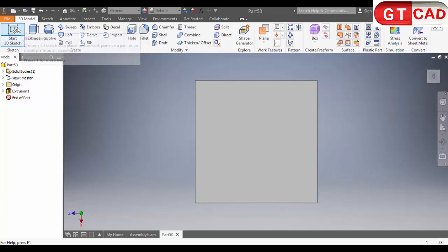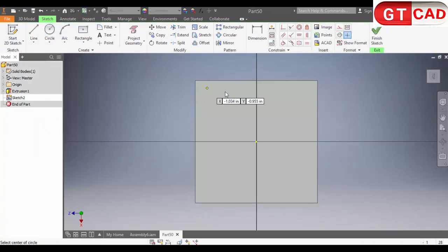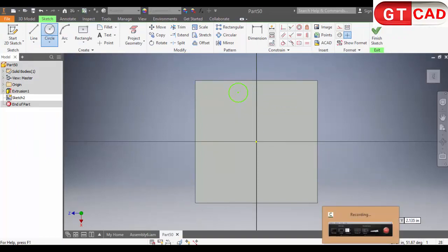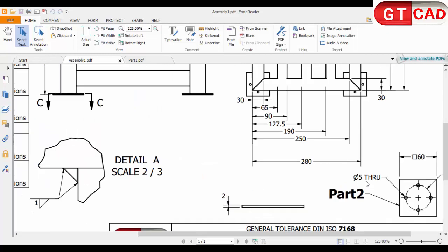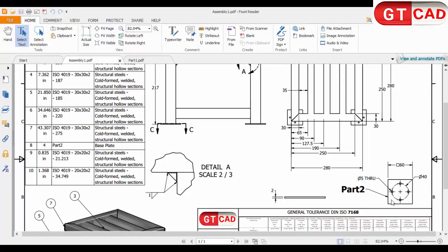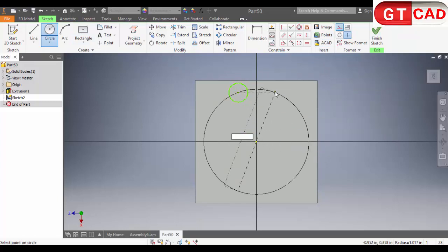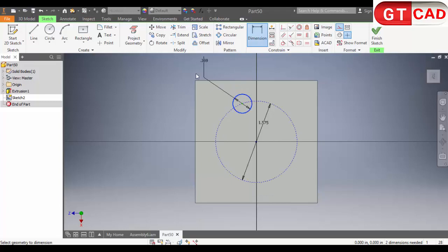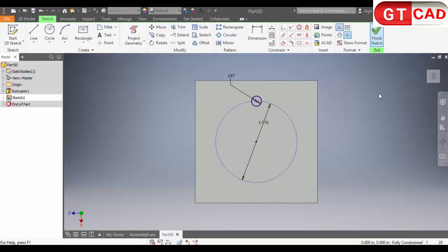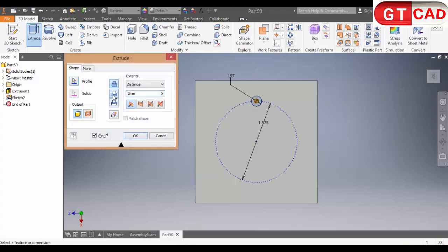We have the hole, sketch it, or you can use the hole option. The diameter of the hole is 5 and the pitch circle pattern is 40 millimeters in diameter. Okay, we have the diameter, but for construction it is 40 millimeters. Make a coincident circle of the hole. It's 5 millimeters. Make a vertical relation from the origin. Okay. Exit. Cut extrude through.